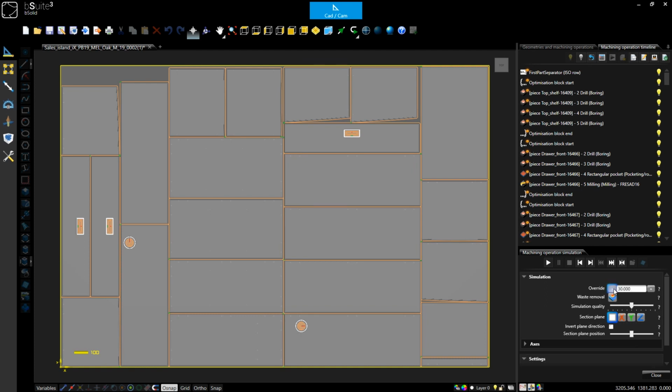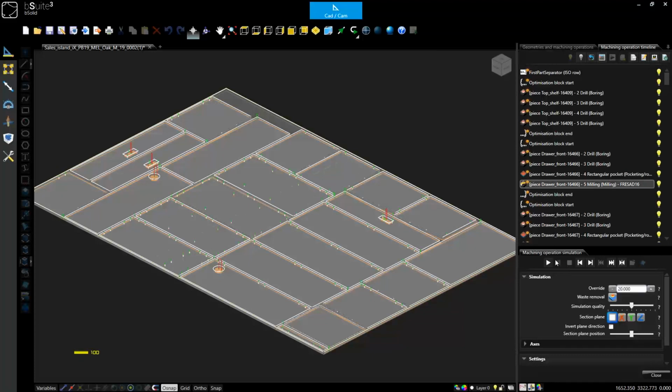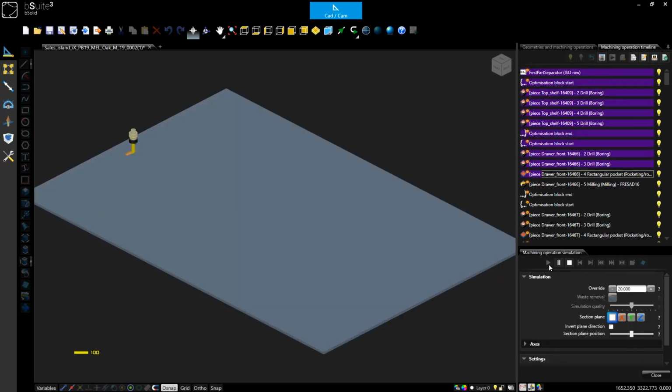Here I'll speed this up at a level of 20. As you can see, all of the tooling has been automatically assigned from imos. All of the tool paths, speeds and directions can be configured from imos or take the default settings from the specific WOP software.